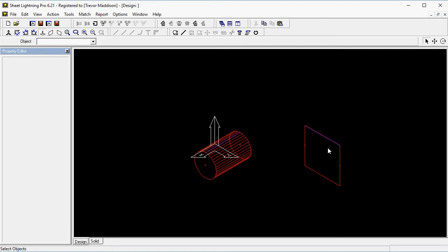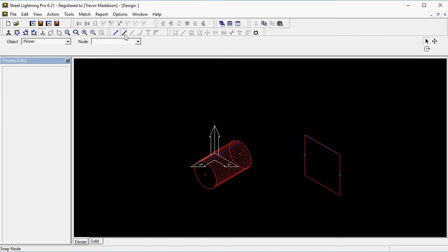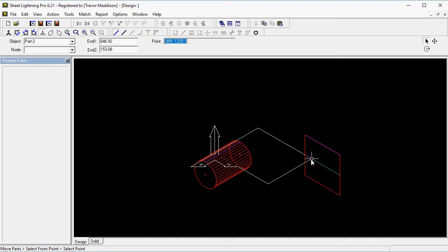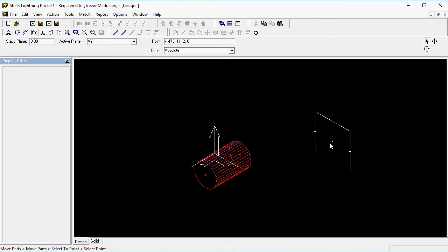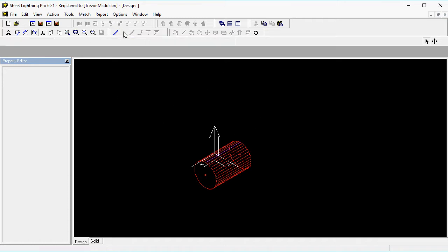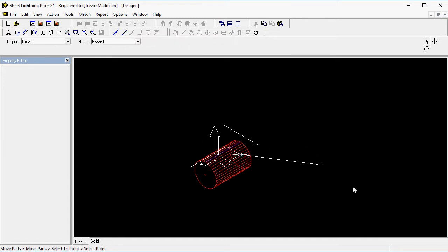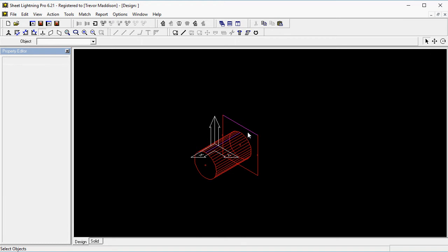So let's click on this part, click on the drag tool, click on the centerline snap, and then snap to this center line, and then we need to type in a position of 400 millimeters. This is 800 long, so we want to get the center, so let's type in 400 here, and that's the point from which it's going to drag it, and in fact link it to this. When I choose snap node, this node is highlighted, and I'm going to snap onto there. So I'm going to use this to cut that.